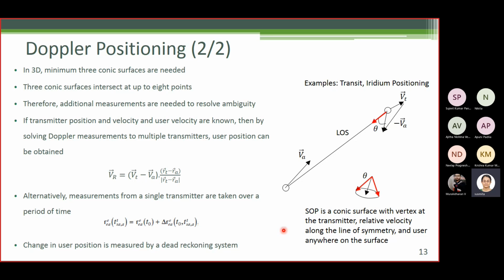One of the requirements would be to correct the INS, inertial navigation system. They use the highest quality inertial navigation system, called navigation grade INS. But still the system drifts over time. The error grows over time. So periodically it has to come to the surface of the water to correct for the errors. So they use Transit signals to correct for INS errors also.